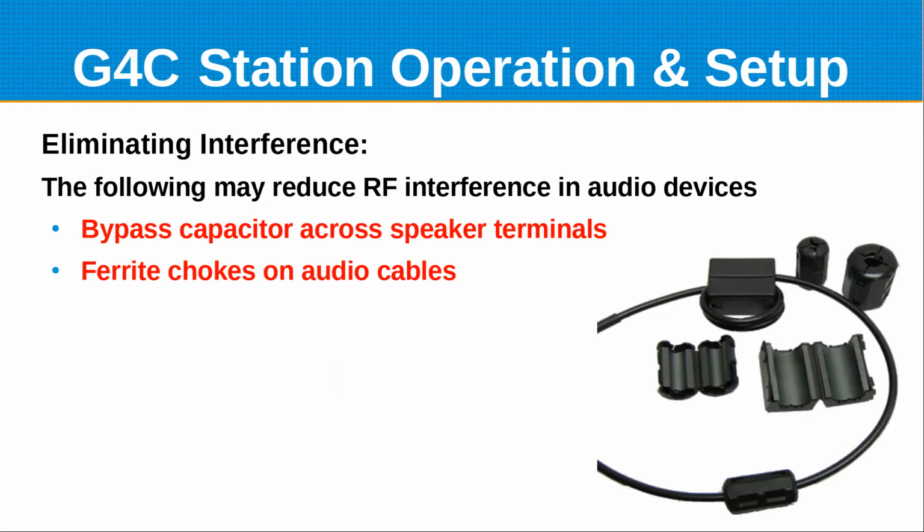Those pictures show what they call clip-ons, where it's actually split, so it's easy to put it over an existing cable where you wouldn't be able to get the connector through the hole. You can buy assortments of those off of Amazon, a box full of different sizes. You can fit them to just about any cable you have. In some cases, you can run several loops through the ferrite, which gives you more inductance and reduces the common mode on the shield.